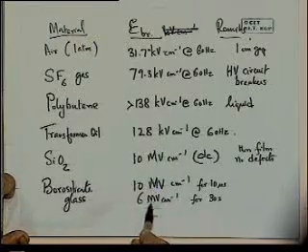So this is sort of built in. As long as my field doesn't exceed 6 megavolts, or 5 to be on the safe side, for more than 10 microseconds, momentarily it may spike. Voltages go spiking in our homes, and your PC, you're protecting it with a UPS and all that. Momentarily it surges. As long as it surges for a very short duration, you can prevent breakdown of that material.